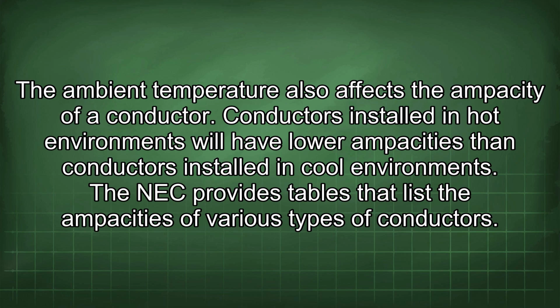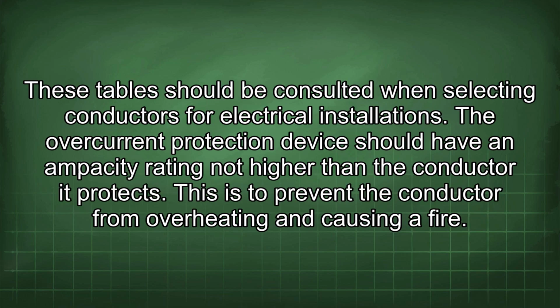The ambient temperature also affects the ampacity of a conductor. Conductors installed in hot environments will have lower ampacities than conductors installed in cool environments. The NEC provides tables that list the ampacities of various types of conductors. These tables should be consulted when selecting conductors for electrical installations.